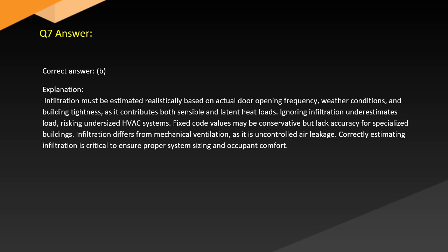Answer. Correct answer: B. Explanation. Infiltration must be estimated realistically based on actual door opening frequency, weather conditions, and building tightness, as it contributes both sensible and latent heat loads. Ignoring infiltration underestimates load, risking undersized HVAC systems.